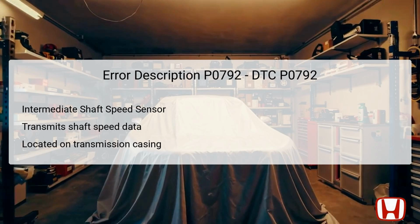Located on the transmission casing, this sensor monitors the rotational speed of the shaft, ensuring accurate shifts and controlling engine and vehicle dynamics. Should the signal from the sensor fall outside the designated range or exhibit performance issues, it triggers the DTC, thus necessitating an inspection.